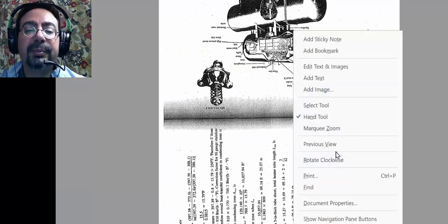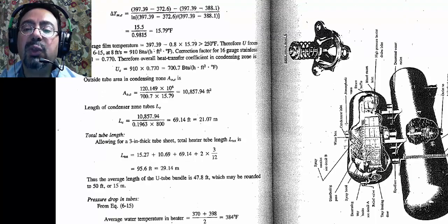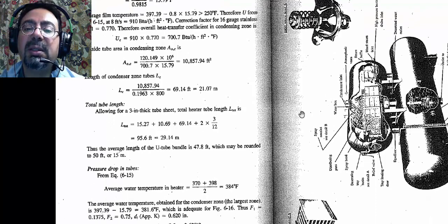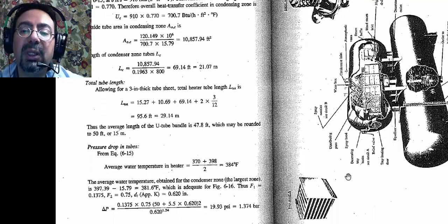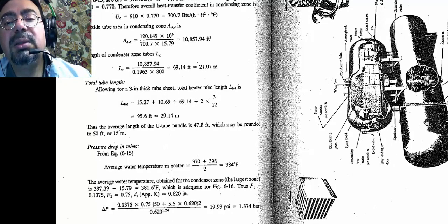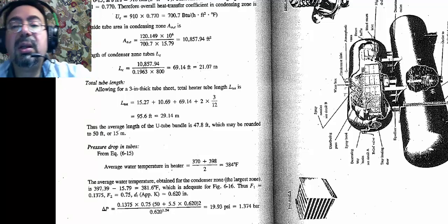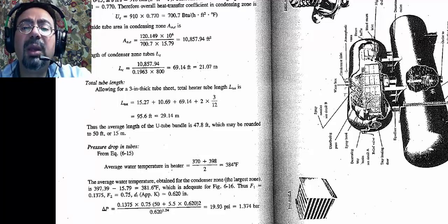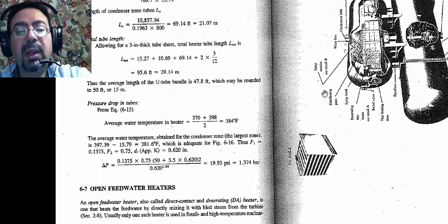Very good. So now the open feed water heater is one big tank, right? Where the steam gets flushed with the water and they all mix. Every power plant has to have one of those open feed water heaters. Why? So that they can liberate any dissolved gases in them. Any O2 or N2 that leaked into the condenser, because it's really running under vacuum, you can liberate them and eject them in that place.